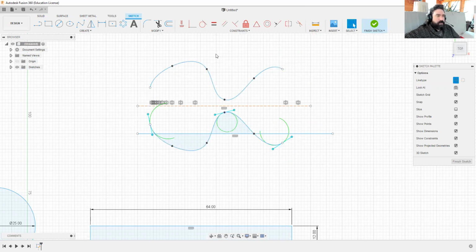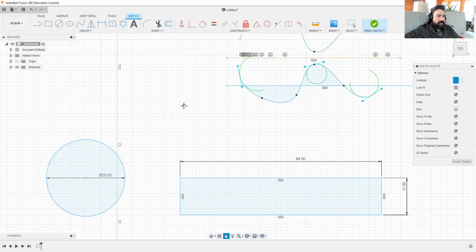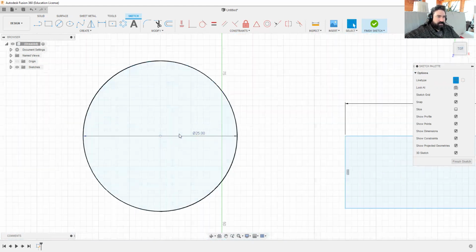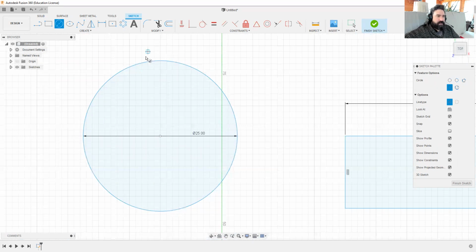Now, what if I want to make something that's based on, say, a circle, but I want to tweak that, maybe I draw some circles along the edge here. See, my mouse is a crosshair, a plus right now, but when I get close to the edge, it changes to an X, and a blue X at that. Same thing on this rectangle, anything like that. What that's showing is that your starting point is on that edge right there. So I'm going to make a circle here. I'm just drawing this out.